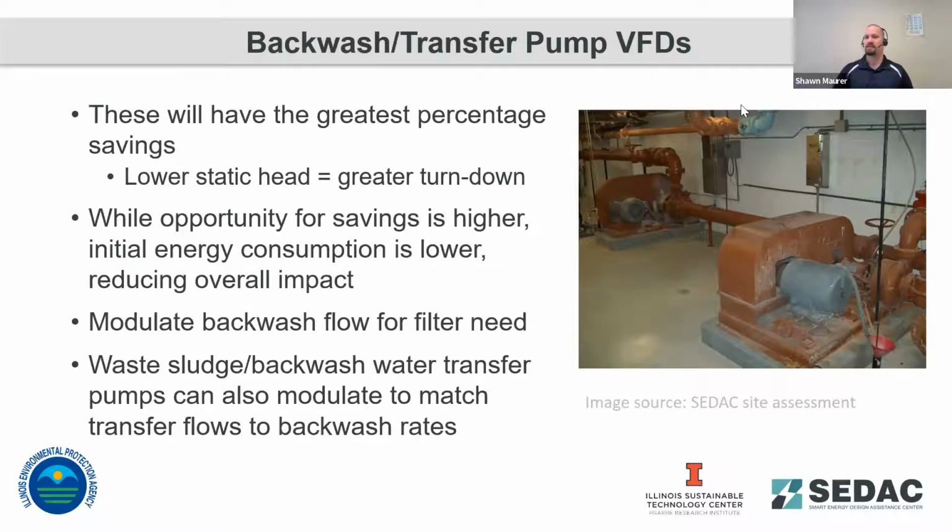A lot of times what we see is that to meet flow rates, you can run multiple pumps at lower speed with VFDs applied to them and get some energy savings that way instead of running one pump at higher speed. So that's a good opportunity if you've got multiple pumps that work together in stages to save energy with a VFD.